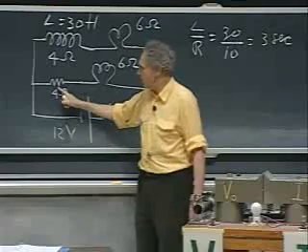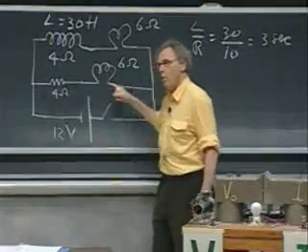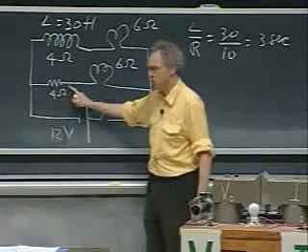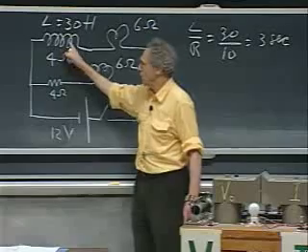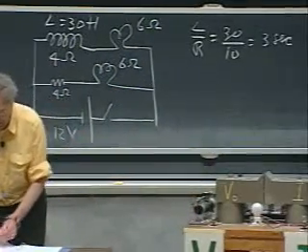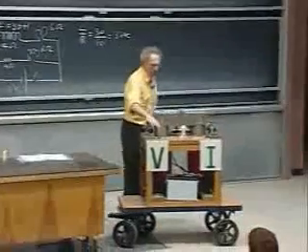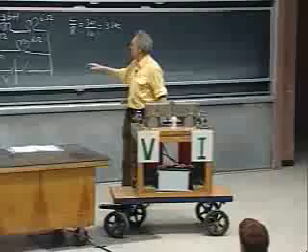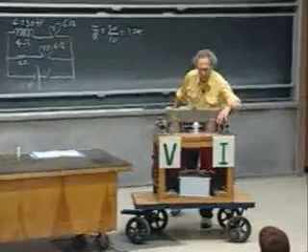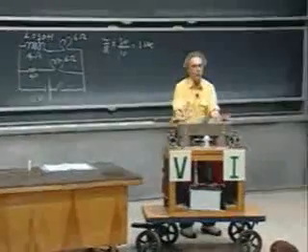The reason why we put the 4 ohm here, we want this part to be, from an ohmic resistance point of view, identical as this part. So that's why we artificially added here the 4 ohm, because the 4 ohm is always there in the self-inductance. There is nothing we can do about it. And so you're going to see a remarkable example. This is one light bulb. That is the one that is here. And this is the light bulb that is there. And the self-inductance is in this incredible monster here.